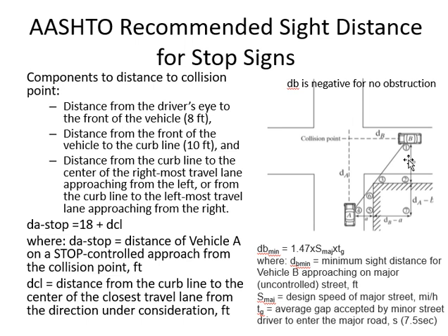Now what is this 18 feet? Where is this 18 feet coming from? These 2 numbers, 8 and 10. 8 is from the car design and 10 is from the safety point of view, plus whatever distance we have from the curb to the conflict point, this one.